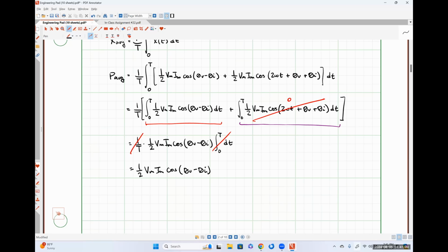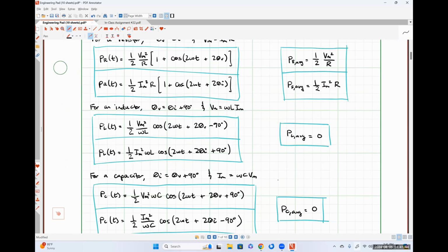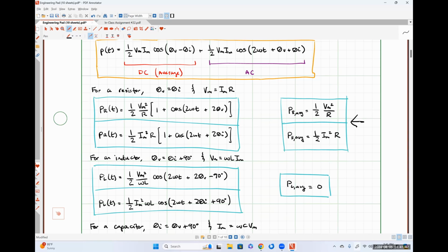And now we have fully, formally, mathematically described it and gotten effectively the same result every different way. So our average power relationship in a steady state sinusoidal system is just going to be 1/2 Vm Im cosine(theta V minus theta I). I'm not going to bore you with deriving these two formally, because it seems to me that if we got this part with our formal definition, these will fall out of that for the same reasoning.